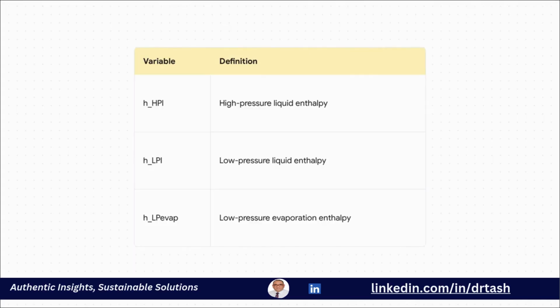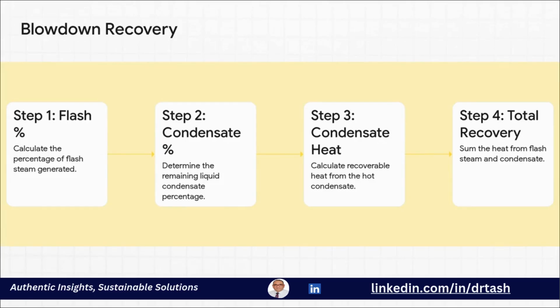And all you have to do is look up a few enthalpy values from a standard steam table, plug them in, and you can model this source of basically free energy with incredible precision. I'm telling you, this calculation right here, it's the absolute foundation for making the business case for any flash steam recovery project. And here's a perfect example of where you'd use it.